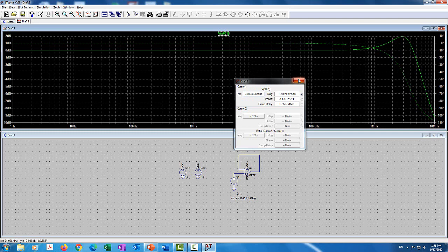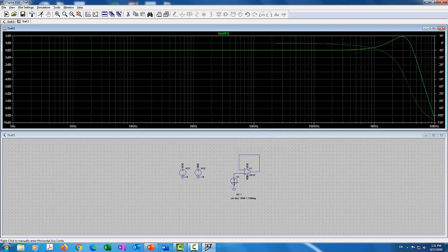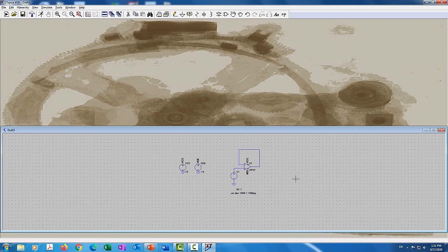So now we're going to investigate the underdamped system, and let's see if we can show you that it's going to be an underdamped system. What I'm going to do here is apply a rectangular pulse and do transient analysis. Again, this frequency response makes sense because the gain is 0 dB, and then it's going to follow the op-amp, and the op-amp is going to degrade as a function of frequency. So let's show you how we're going to do that.